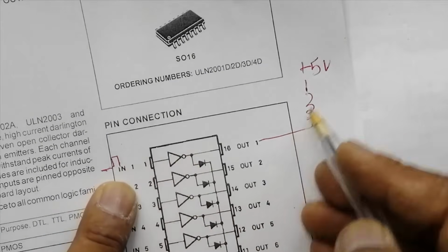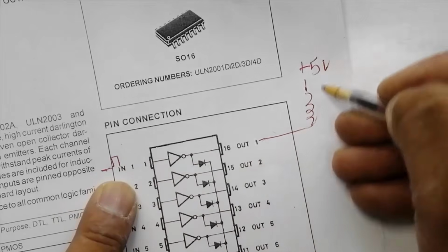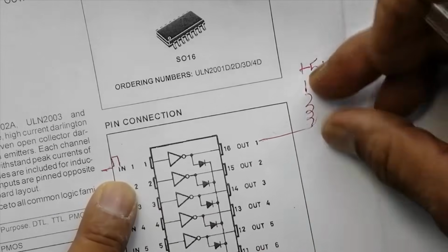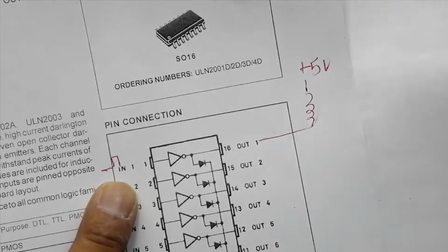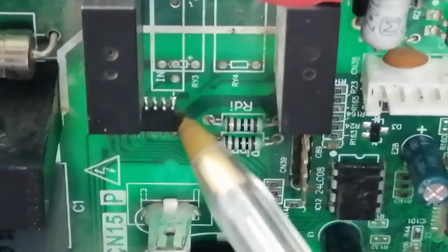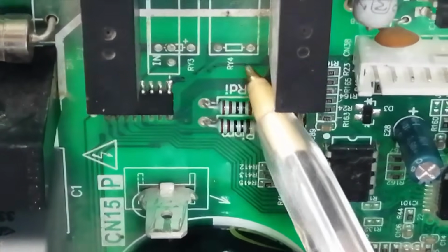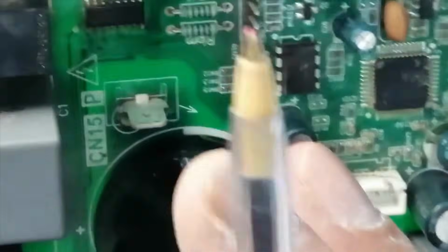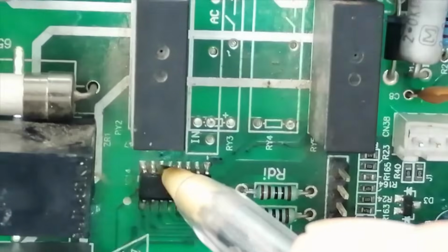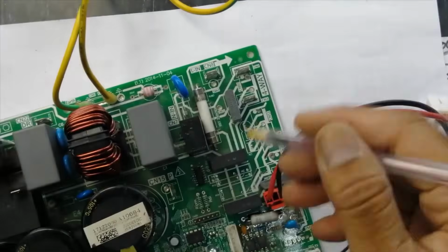So it will switch pin number 1, it will apply ground to this pin and the relay will activate and we will take some necessary function from this one. Here is ULN2003. If we see, this track is the output side and this track is connected to this relay. At the same time there is one other track that is hidden here. This pin will connect to this relay. These are relays. What is the function of these relays? These control the four-way valve.